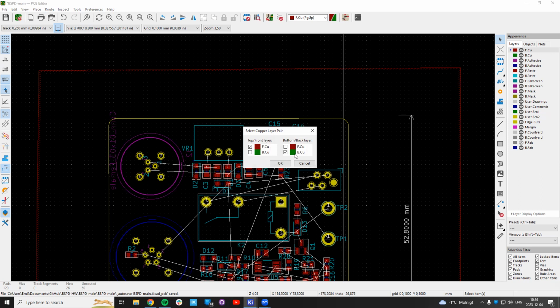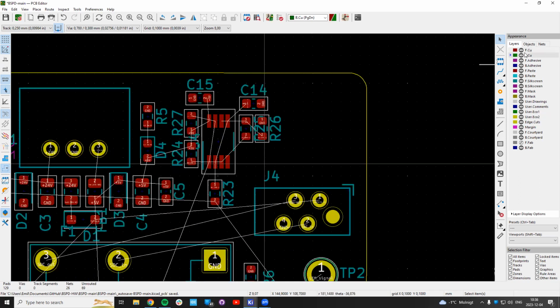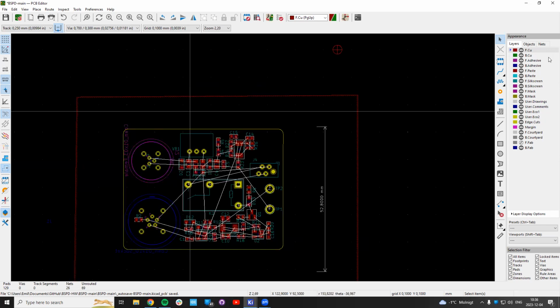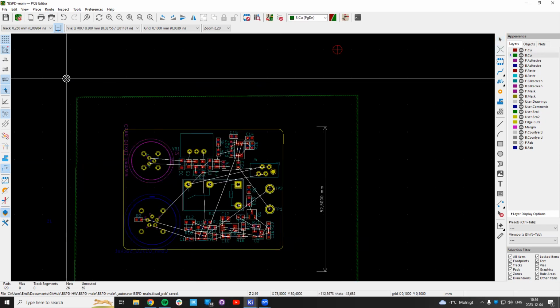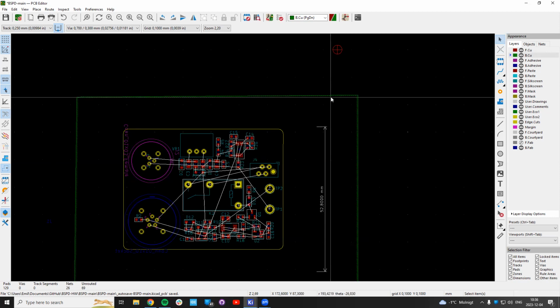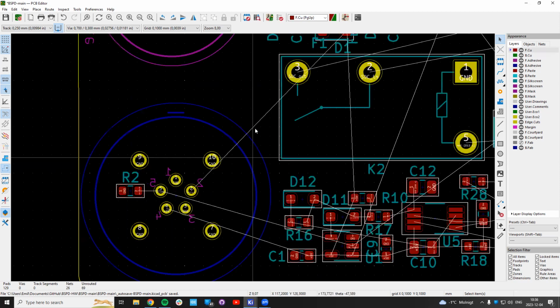If you're doing routing, like if I press V, I switch between these 2 layers. If you have more layers here, you can set it up so that you're switching between other layers, if your signal layers are, for example, the layers in the middle. Anyways, we said we only have 2 layers. The back copper layer is our ground return path. We do not want to place components there, so we're gonna do the routing on the front copper layer.